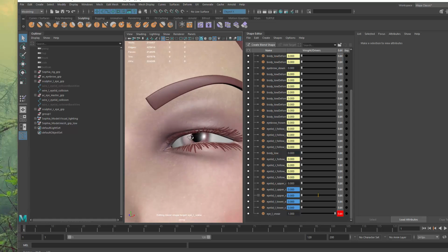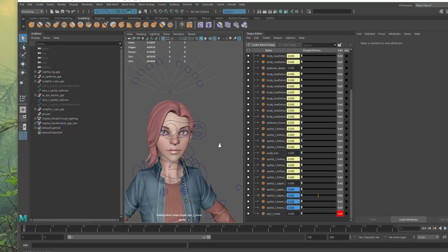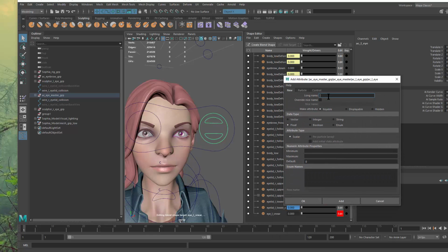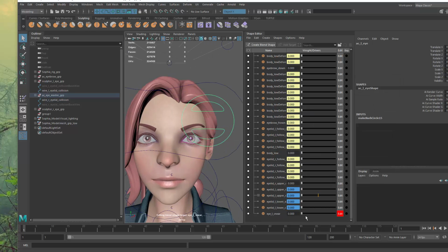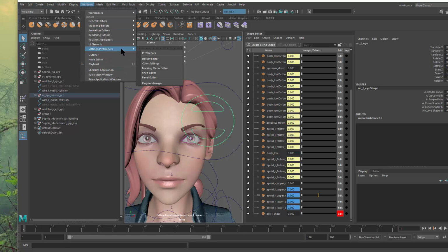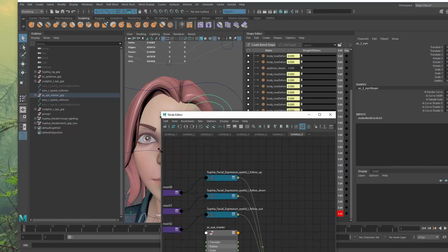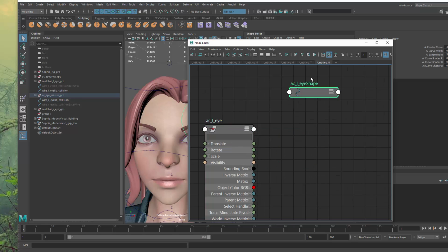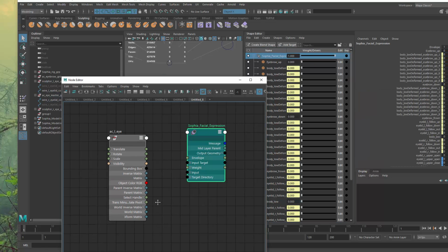All right, I think that's pretty much there. And I just need to create an attribute to control that. It's gonna be a sneer attribute on my eye directional control. Sneer. The value will be from 0 to 1, and because my attribute here, the blend shape, is also from 0 to 1, I can safely go for a connection here. So I can use my controller, add it in, and then the blend shape, add that in, and connect from,